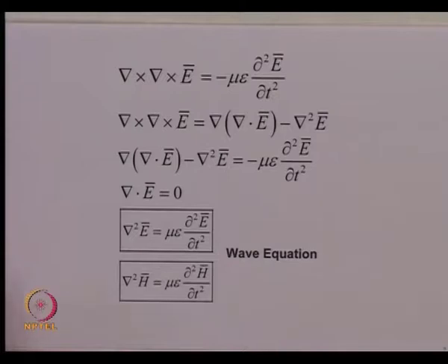So now what we do is we essentially try to solve the wave equation with the physical understanding which we have developed using the ray model, apply appropriate boundary conditions to this, and then get the analytical form of the electric and magnetic fields which would survive inside the core of the optical fiber.